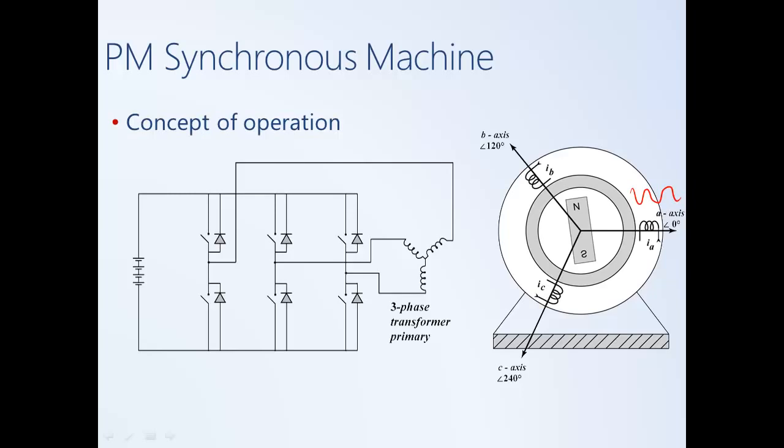It's alternating current, and that alternating current is approximated from a DC source, from a battery, using an inverter like this. And so by changing the frequency and the order in which these switches are opened and closed, we can approximate alternating current in each of the three phases, which you can see here. So it may not be perfectly sinusoidal, but we can approximate it with small steps.